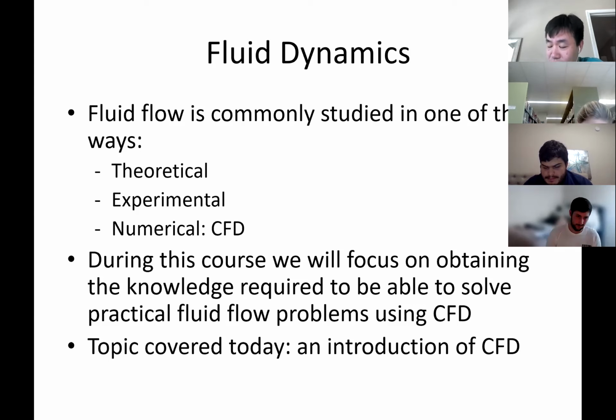So if the size becomes 10 times smaller, then you have to play with the properties. You can't just shoot air at the airplane for the test. You have to decrease the viscosity 10 times, or increase the density of the fluid 10 times, which is not air anymore, to ensure the same Reynolds number between your scaled test and reality.